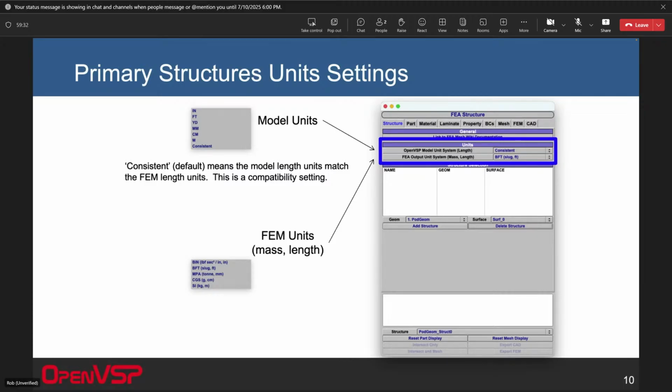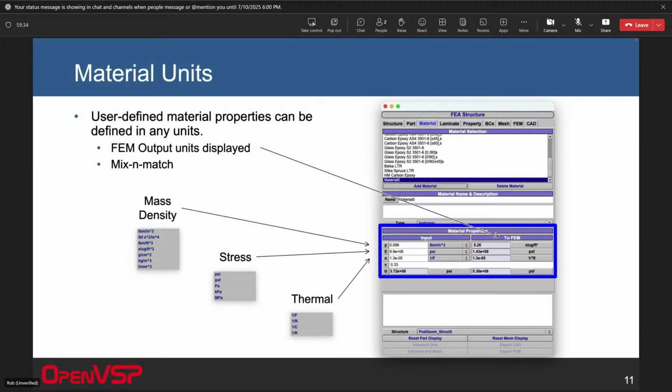for these definitions are. When you're specifying materials, if you look up some material property online, what I've found is that, as I said, you can't ever trust what units those are going to come in. If you find 5 different materials, they're going to come in 10 different sets of units. So if you're putting in user-defined materials, then you're going to specify exactly the units for each of the material properties that you use as you find them.